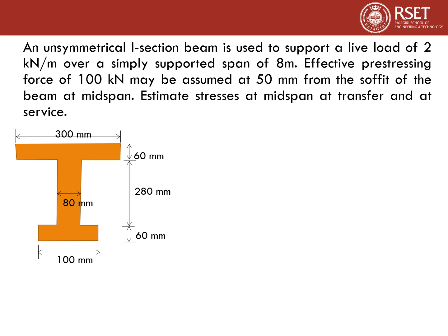So there are two stages of checking for stresses, that is at transfer and at service. At transfer, it is soon after the pre-stressing is applied. Here we need to check only for dead load and not live load. At service, we have to consider all the cases: pre-stressing force, dead load and live load.